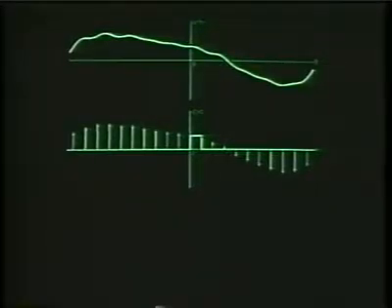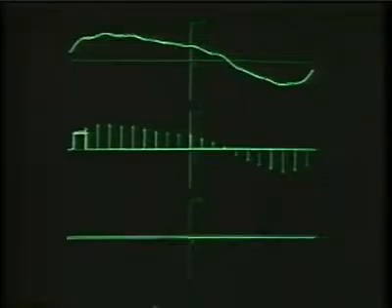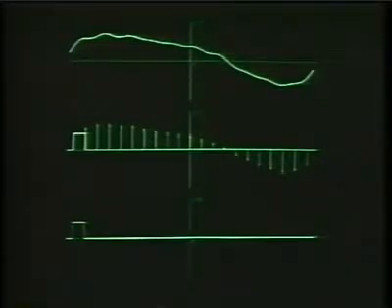Now, to build up the interpolation, what we'll have is one of those at each sample time, and those are added together. We'll start that process as we did before at the left-hand end of the set of samples and build the interpolating signal on the bottom. So with the left-hand sample, we have first the rectangle associated with that. That's shown now on the bottom curve. We now have an interpolating rectangle with the second sample that gets added into the bottom curve.